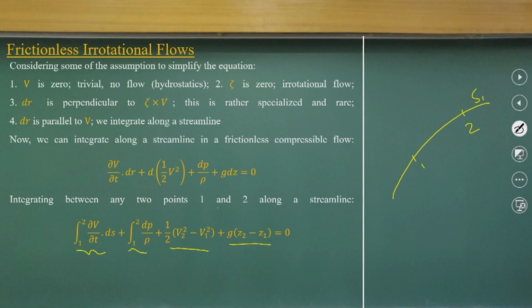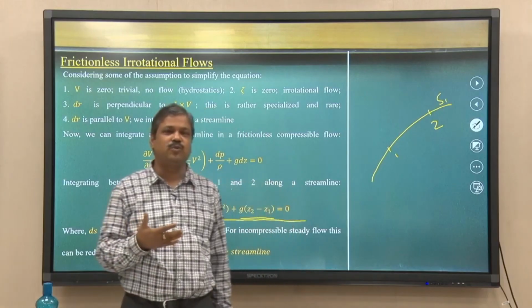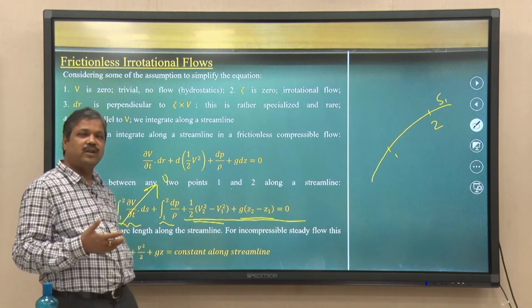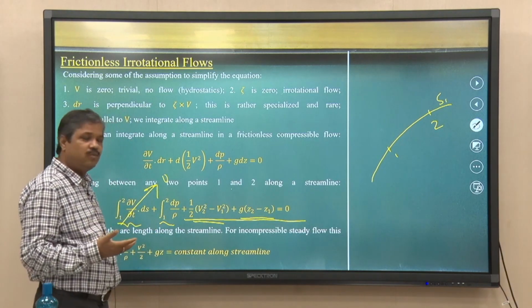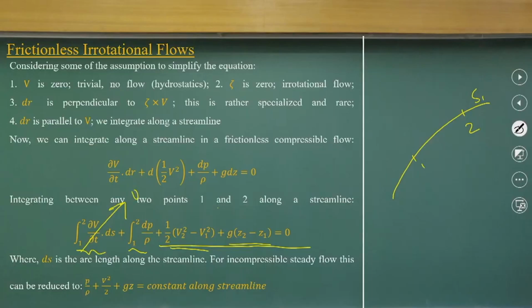Further, if you simplify it, that is a steady flow. If you have an unsteady flow, you can always start with these components of Bernoulli's equation. That is what we should practice: if you are solving unsteady flows, you can start with these 3 components along the streamline to get how the velocity varies and how the pressure varies.